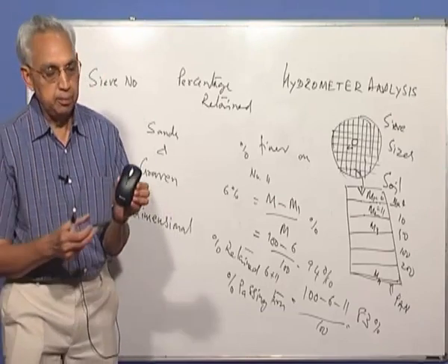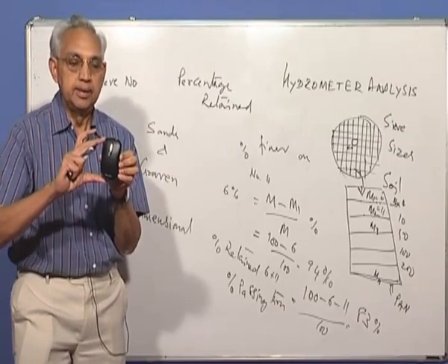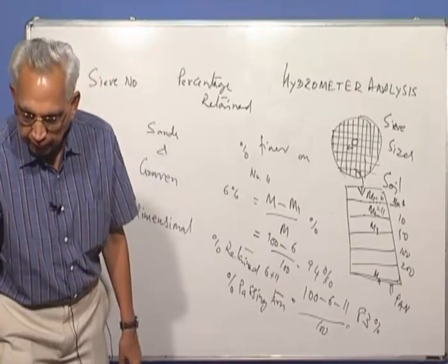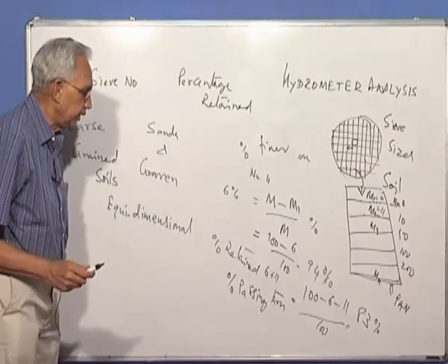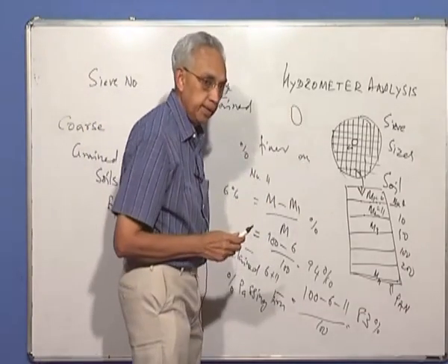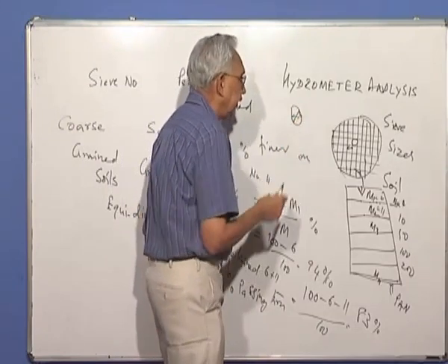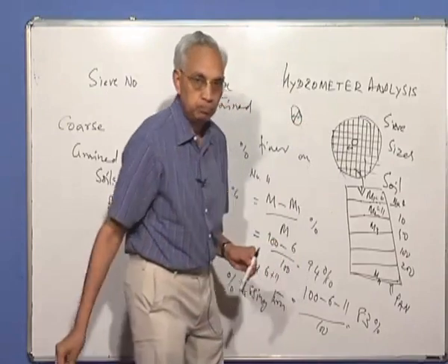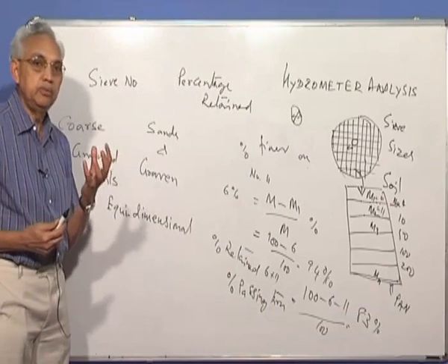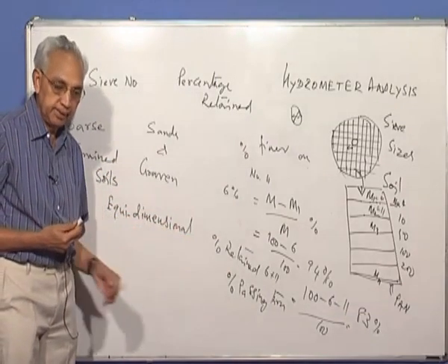Again, another example would be one dimension here, second dimension here, third dimension. Don't look at it, the actual size could be much smaller. This is the characteristic of coarse grained material. So what it means is, suppose I have a slightly longish particle. If the two horizontal directions are the same, the particle can go through. So what it will tell you in terms of sizes is the size through which a grain can fall through, and that will give me how much is passing through the size.